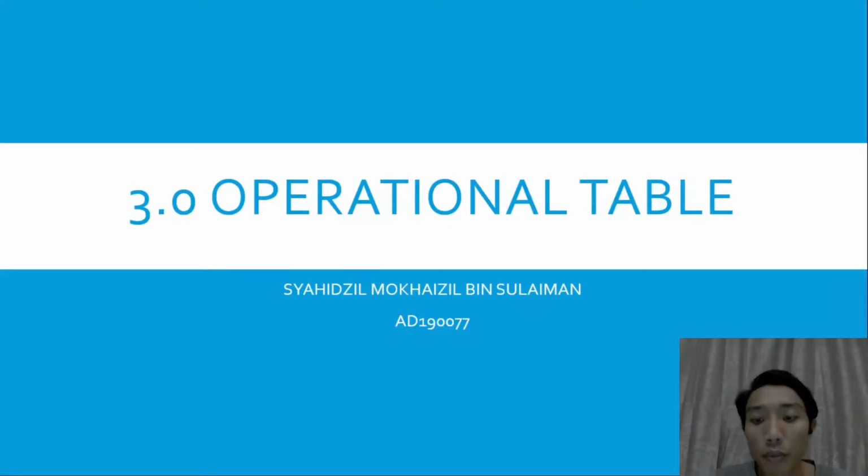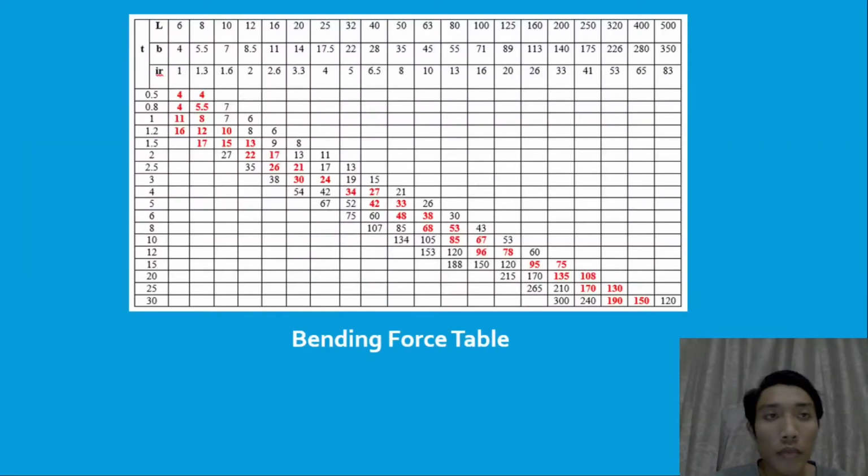Assalamu alaikum warahmatullahi wabarakatuh. In this video, I'm going to talk about our group operational table. First things first, this is the bending force table. It guides us to identify the suitable dimensions for our group metal bending. To make it clearer, let's say I have a 2 mm thick sheet and I want to bend it. I also use a 2 mm inside radius IR.